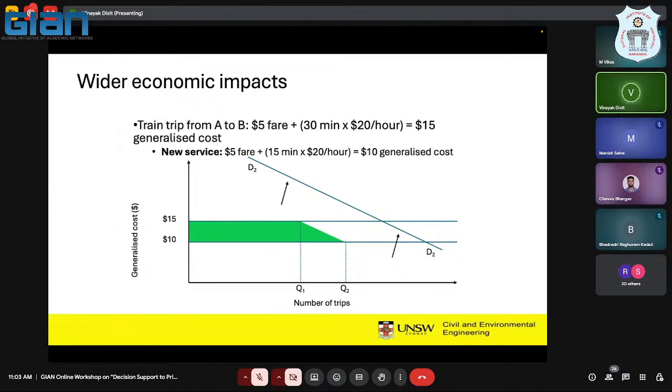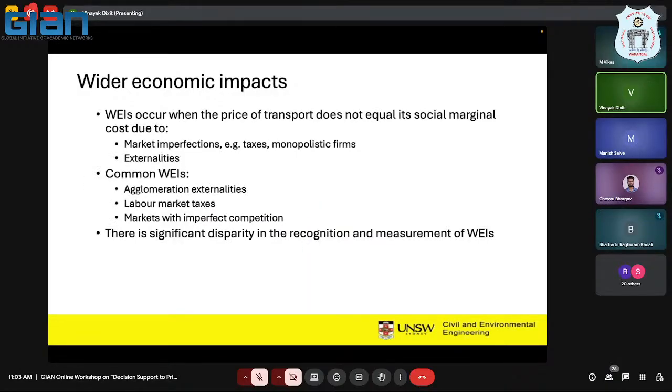In Visum, endogenously, you can't. So what you do is you do an analysis before and you say that because you have put in this road, we are expecting a growth in economy by 5%. So based on that, I forecast that the ODs here will change. But then you implement those ODs and then evaluate what the benefits are. But in transport economics, we have something called a CGE model where it tells you what the ODs will come up. The new ODs will come up on its own. Okay, sir. Got it.